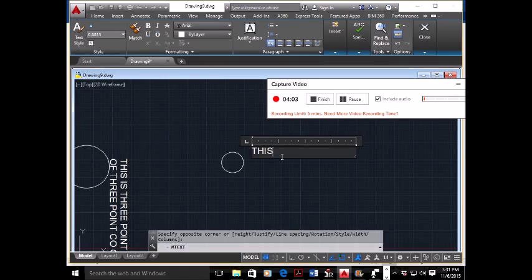On the ribbon, make format changes as follows. To change the font of the selected text, select a font from the list. To change the height of the selected text, enter a new value in the height box. Please note that the text height value is reset to 0 if its default height is not modified during creation.